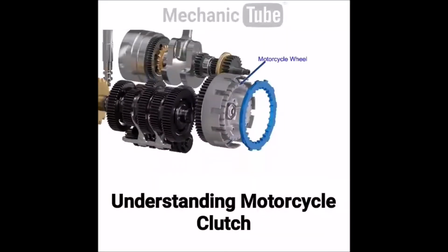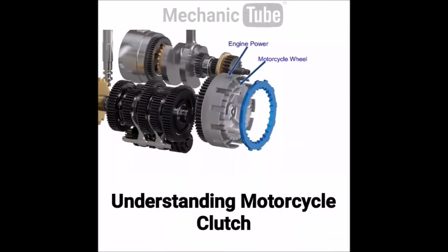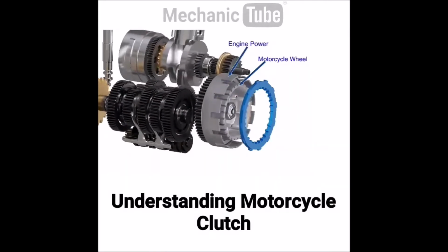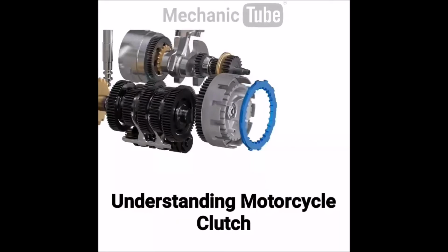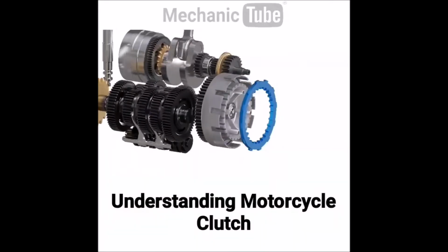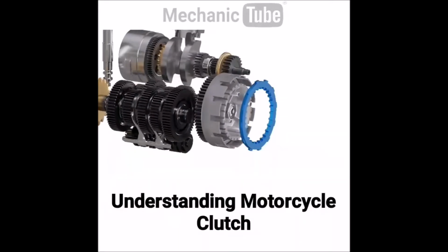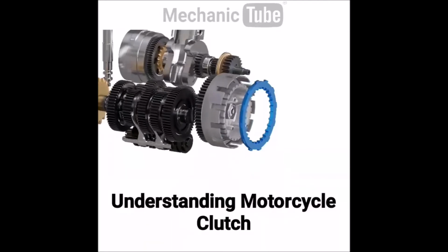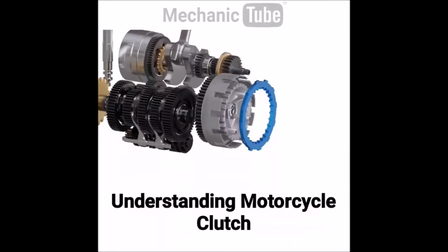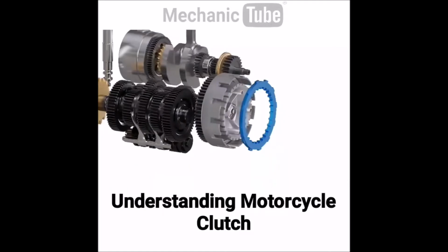Due to inertia of the motorcycle rear wheel, the inner hub spins, and the outer basket spins due to engine power. This is why these two components start spinning at different speeds. In order to interlock with both of these non-synchronized spinning components, the hypothetical connector will have to spin at 2 different speeds at the same time, which is impossible.